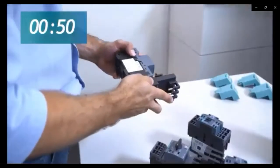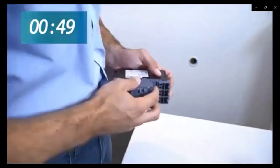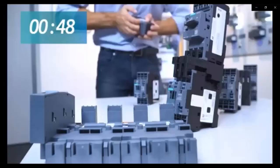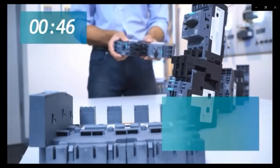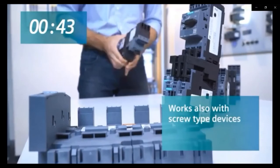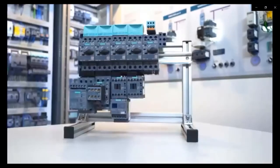I have to mention that one of the biggest advantages with the infeed system is that it allows you to change devices under voltage, not under load, but still when voltage is present. And when the links are removed, you have a perfect visual of the three phases disconnected. The infeed system also remains finger-proof even when the starters are removed.